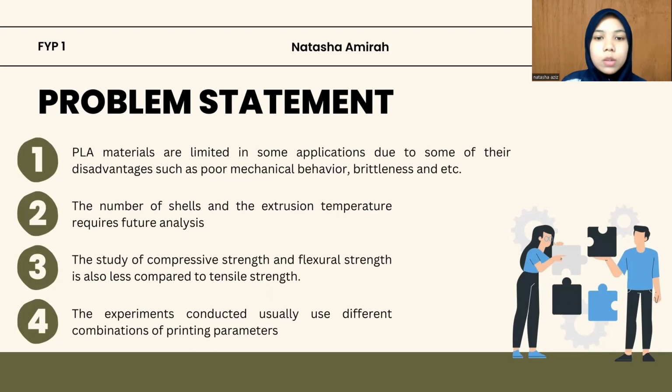Next, the number of shells and the extrusion temperature require further analysis to improve dimensional accuracy, because most existing studies only consider 2 or 3 common parameters. Therefore, more parameters such as filling pattern, nozzle diameter, and extrusion temperature need to be studied to get accurate results.